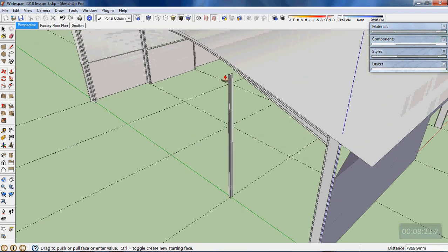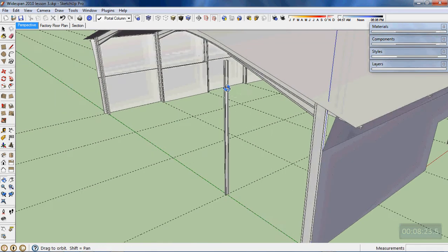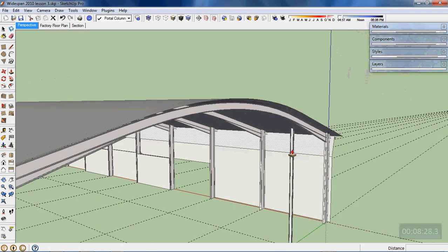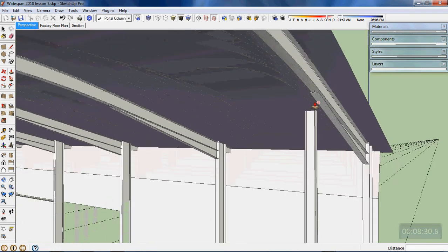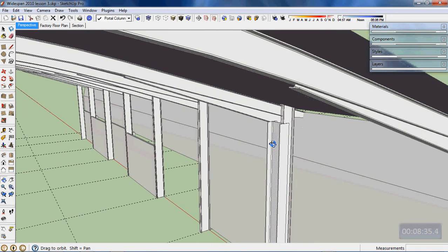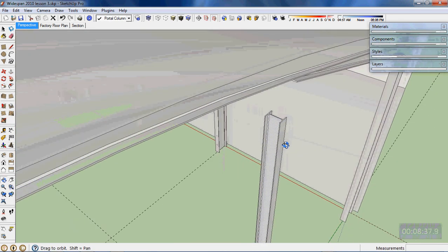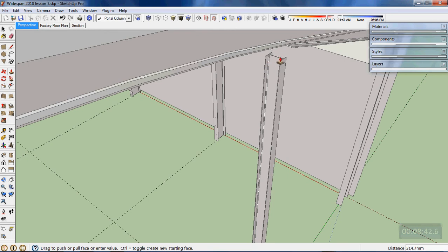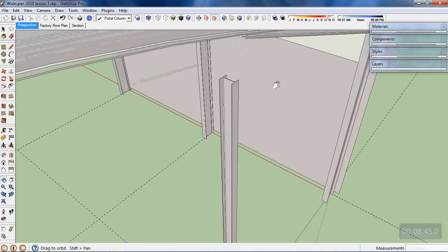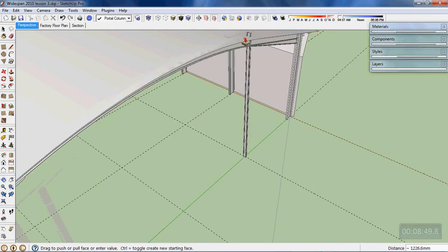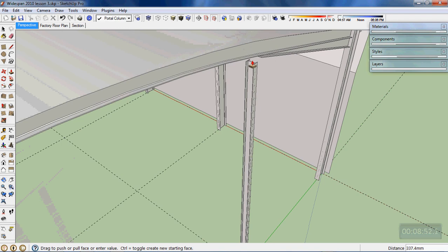Now let's decide how high we're going to take this. We won't actually make it connect perfectly to the rafter because we'd like to be able to triple click it in future. So I'll just go even by eye, it'll be a structural detail, just even by eye, and then we can maybe orbit round. So I'm doing all of this as I'm still holding my left mouse button down with my finger, and then I'm using my other finger to do the scrolling.